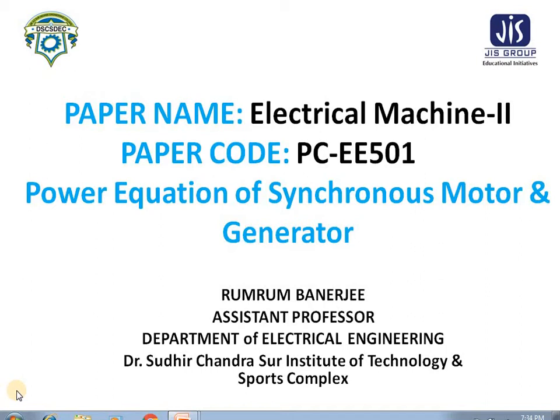It runs either at synchronous speed or not at all. While running, it maintains constant speed, independent of load. Secondly, it is not inherently self-starting. It has to be brought up to synchronous speed by some means before it can be synchronized to the supply. It can be operated under a wide range of power factors, both lagging and leading. And it will stall if the load torque is beyond the maximum torque that the machine can develop.